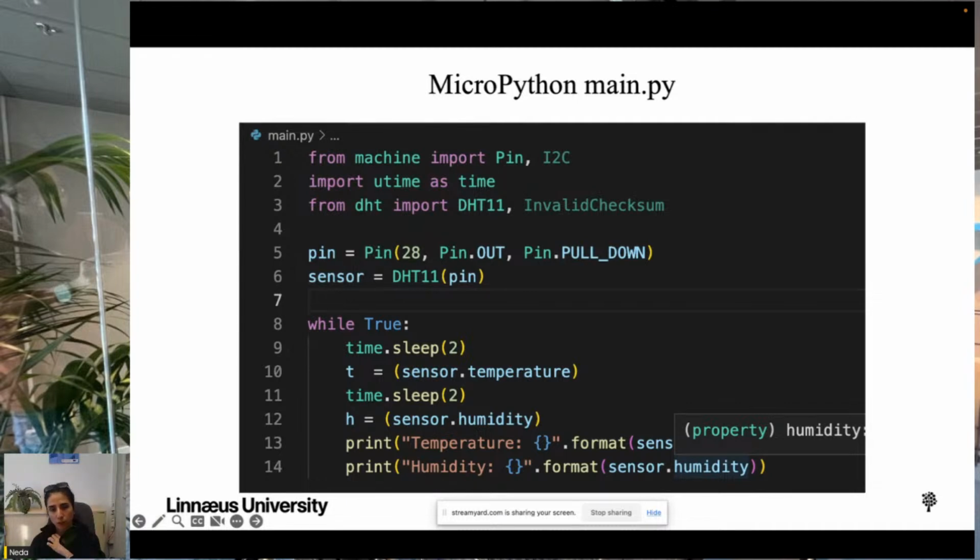When we use Pin.OUT in our code, we are telling the microcontroller to configure that particular pin as an output pin. So this is what Pin.OUT means. But what does Pin.PULL_DOWN mean? In MicroPython, Pin.PULL_DOWN is used to enable a pull-down resistor on a GPIO pin. A pull-down resistor is a component that is used to ensure that a pin has a predictable voltage level when it is not being actively driven by the microcontroller.